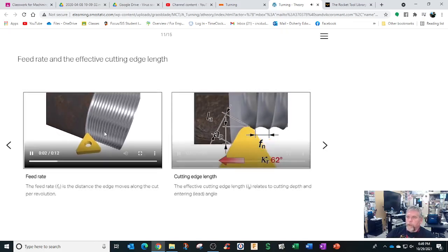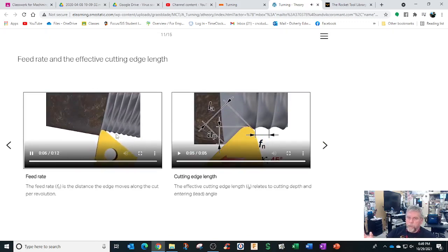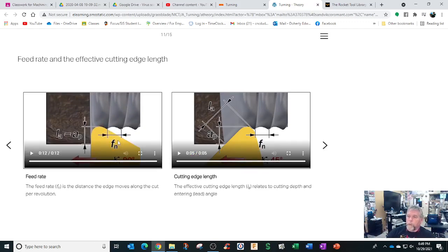And effect, you get feed rate. Now, if you ran a faster feed rate, the spaces between each would be very coarse, and you'd have a rough finish. You'd have a uniform finish, but you know, how you cut that, and also which way the insert points. So this one has less contact area, and this one's got more contact area.